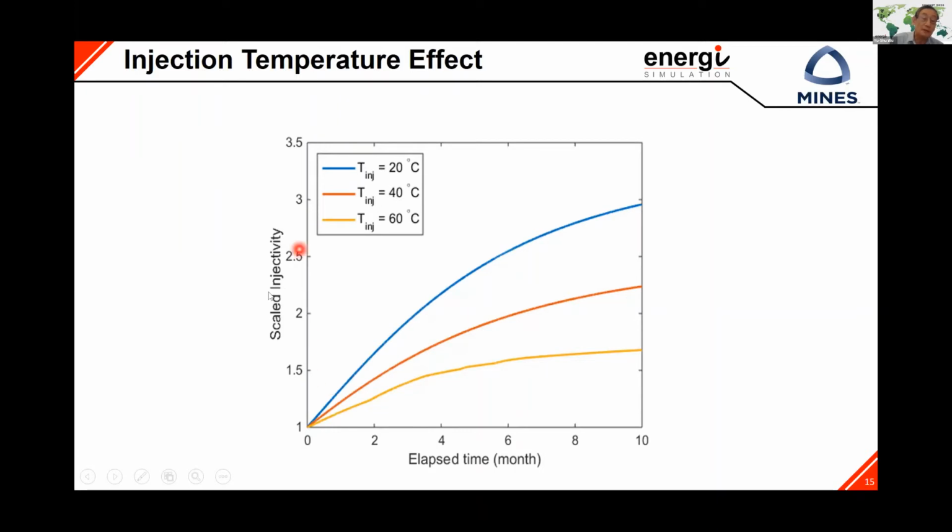Here, really, it's a big deal for unconventional reservoirs. Injecting liquid normally is not okay, right? Because of low permeability. Why does CO2 work? Because CO2, even in the supercritical or gas or liquid phase, still has very low viscosity. We can inject CO2 into tight reservoirs.